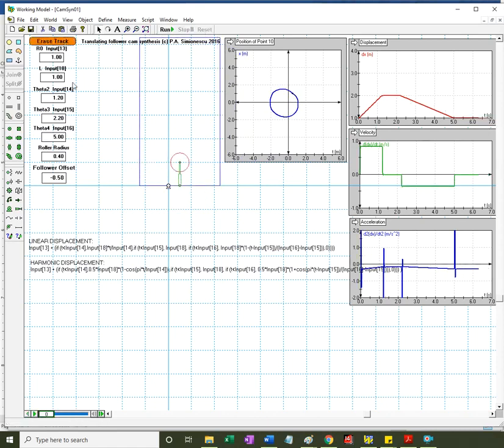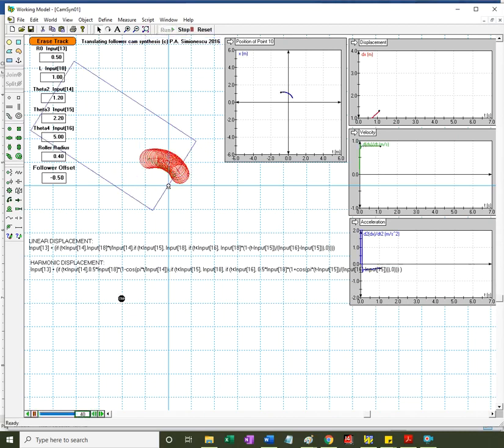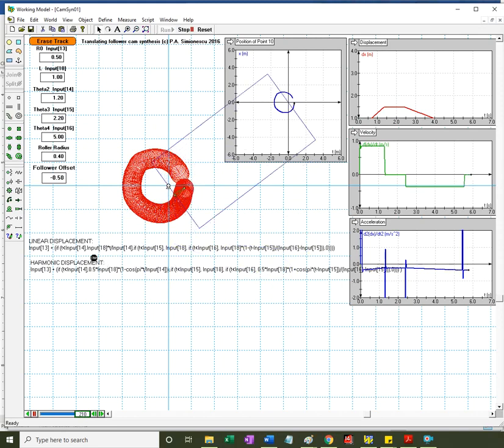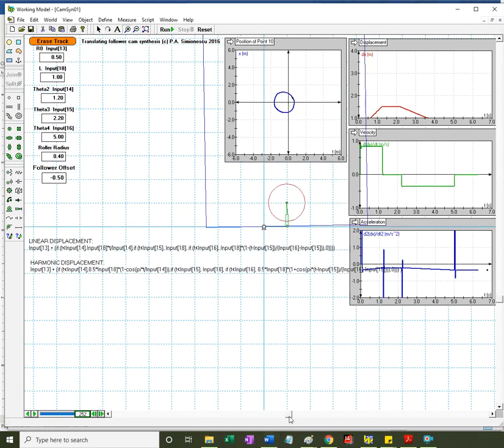Okay, the bias, follower bias. So it does not start at 0. I cannot have a cam of 0 minor circle, or was it called the base circle? I can make it smaller, and if I have it smaller, I'm going to probably see what it's called: undercut.